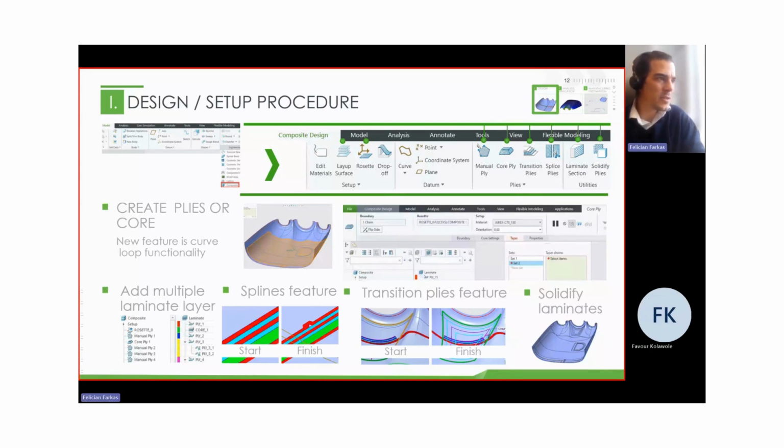So the first stage of designing the geometry, and for that we need to select our layer surface. You can see on the top with the green dot, highlighted with the first green dot. So on that tab, we're selecting our layer surface, which can be solid or quilt, and also the stacking direction, which direction we want to build up the layers, either inside or outside of the layer surface.